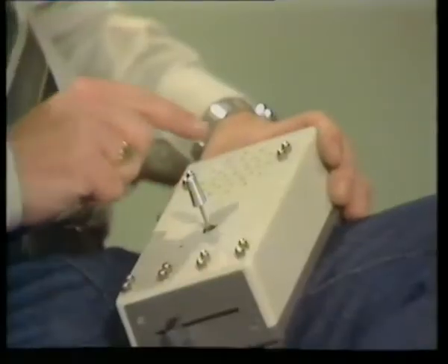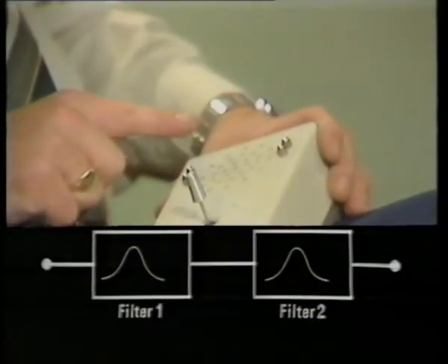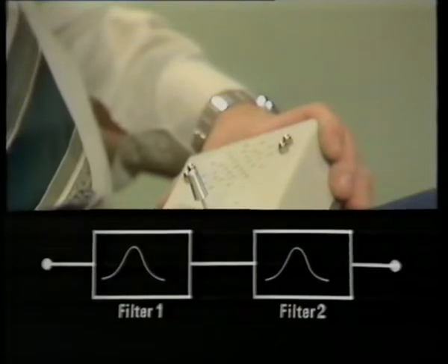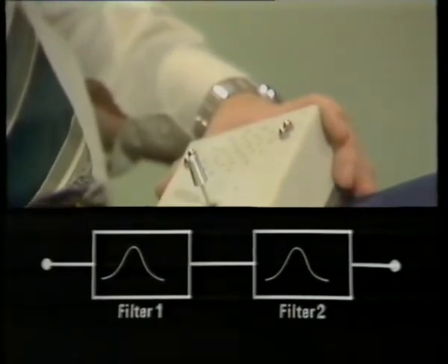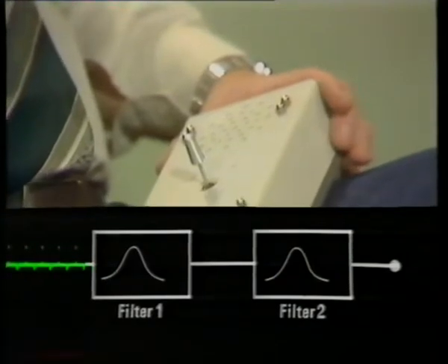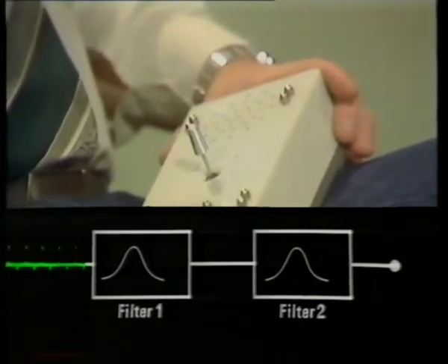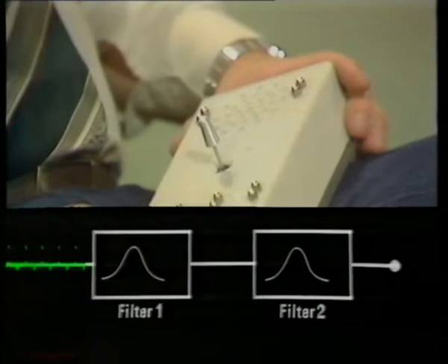Well, I haven't got a filter here with 4 or so peaks, but I've got one with just 2. And even so, it certainly gives voice-like sounds. Its inventors call it a chatterbox. Let's see how it works. It's got 2 filters in cascade, each with just 1 peak. So the overall frequency response is going to have a 2-peak characteristic. And I'm going to feed in a stream of pulses to the input. That's to simulate the excitation produced by the vocal cords.